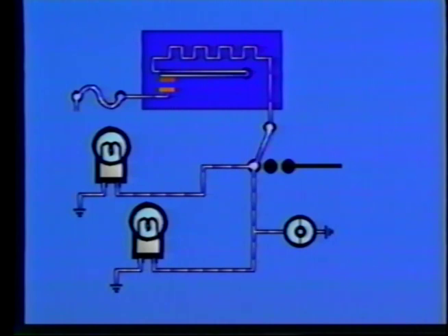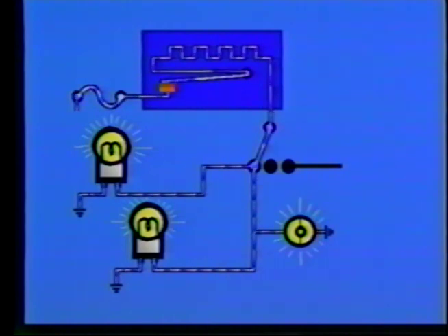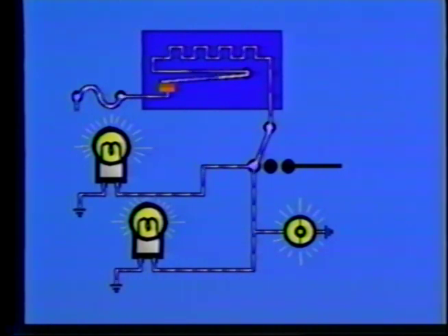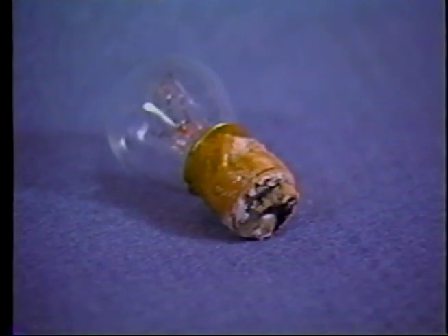How quickly the flasher opens and closes the circuit is directly related to system voltage and amperage flow in the circuit. A charging system which is overcharging will make the directionals flash too quickly. Likewise, an undercharging system will cause the directionals to flash slower. Circuit resistance also affects the rate of flashing. Bulbs of high resistance or corrosion in the circuit can make the system flash slower due to reduced current flow in the circuit. If bulbs of lower resistance than specified are used, the system will flash too rapidly. In a similar manner, incorrect flasher applications can cause the wrong rate of flash.